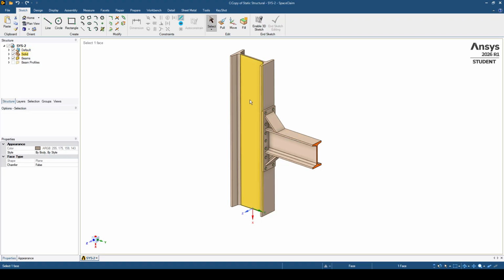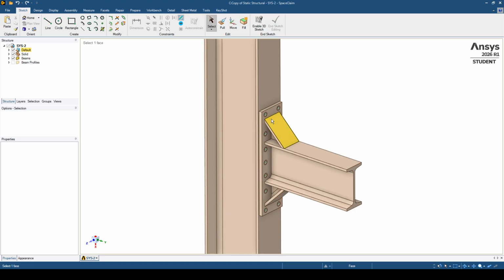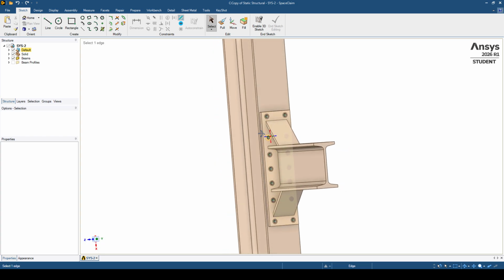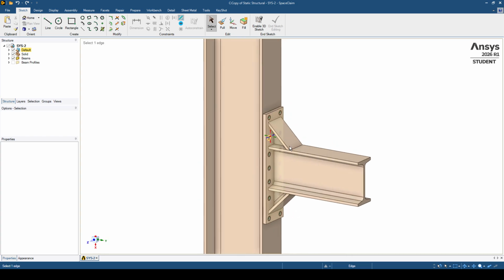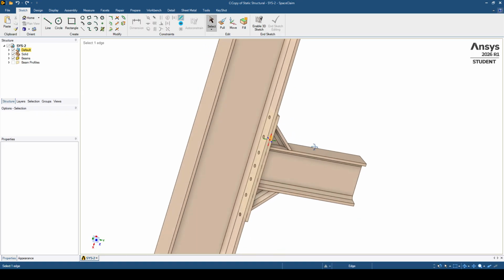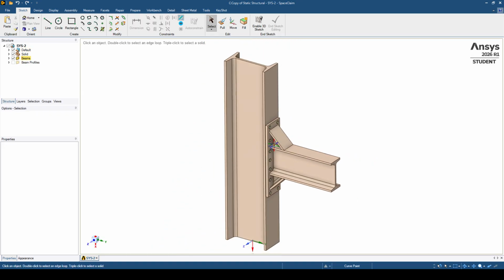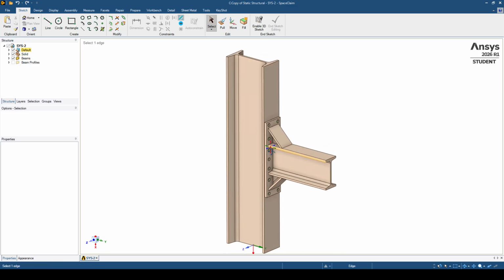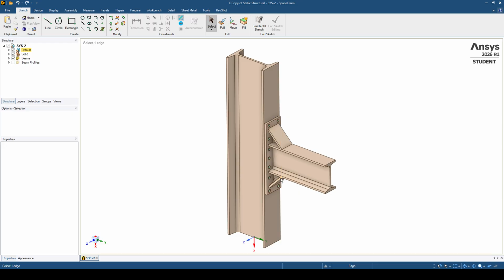In this analysis, what we have to prepare first are the steel parts, which is the profile. What you have to do in the geometry phase is to model the beams which represent the bolts. Because we have multiple bolts at these locations and they seem stiff enough, modeling the bolt as a beam will be enough to represent the load acting on that bolt and see if the bolts are okay or not.